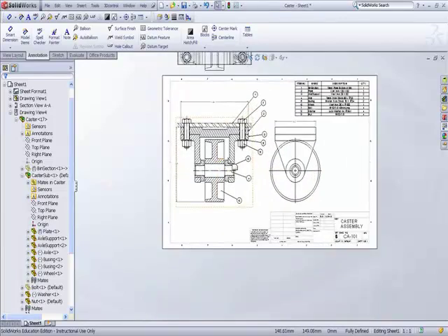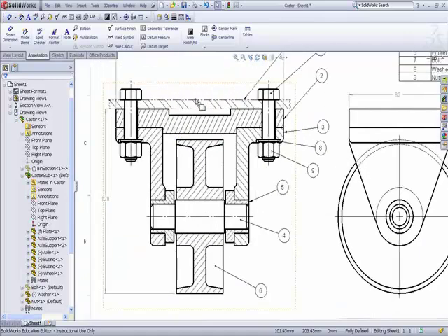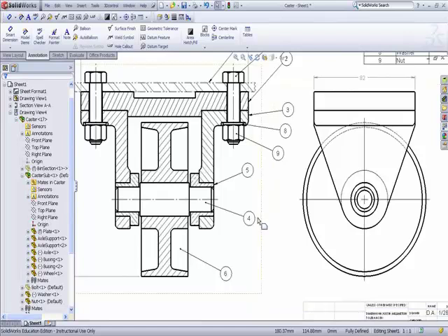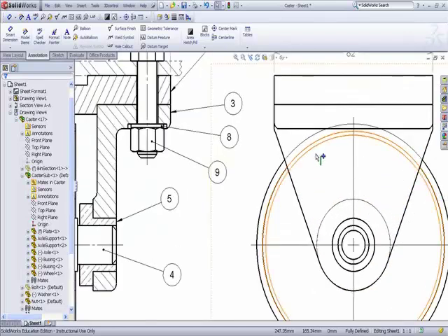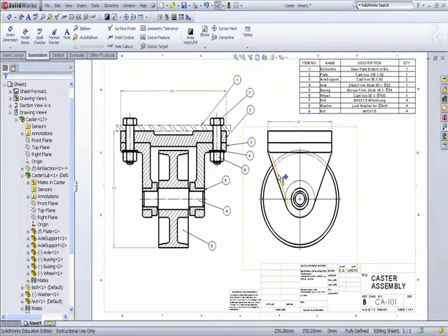If you're happy with the way that looks, you can go ahead and save it now. You can see I've got my line weights, got the phantom lines, the sections look proper. And as far as I can tell on this last review, everything I need is there. This is not necessary to put those hidden lines in, but I'm going to do it anyway. So at this point, you can go ahead and plot it and save it. And that's the end of the drawing video.